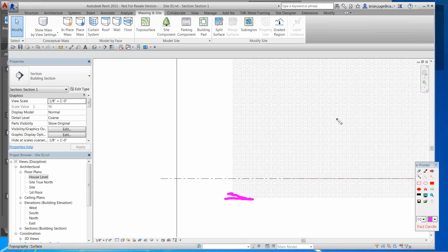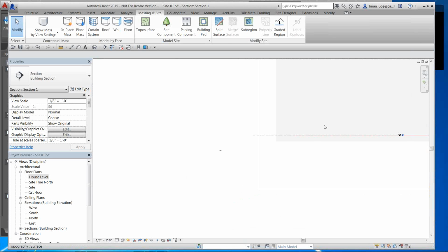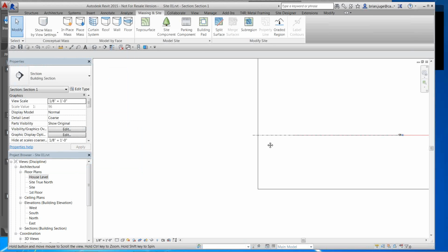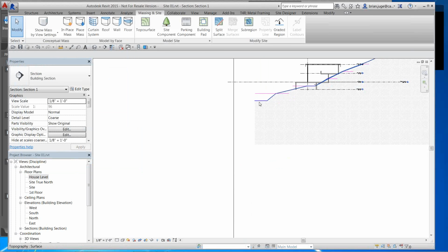And you're always going to be cropping this out and trying to figure out, well, why do I have so much ground in here? Well, that has to do with this area in here saying elevation bottom. So I'm going to come in here and put this in at 590, hit apply, and you'll see that disappear. And it didn't disappear, it just shrunk up to be 500, starting at 590 feet. So that just gives you an ability to control that. Get an excavator to work that fast. Yeah. So now we've got that in here, kind of set it up.